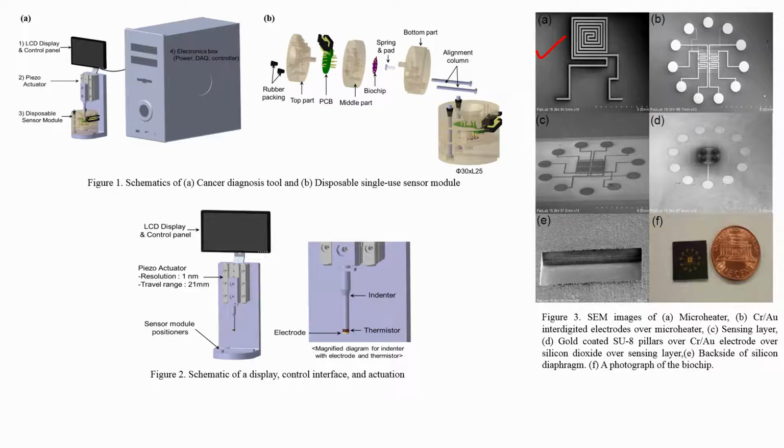After the heater you have an insulating material. On the insulating material you can have interdigitated electrodes. Once you have interdigitated electrodes, again you know how you can fabricate them. You deposit metal and use a lithography technique to form interdigitated electrodes. On these interdigitated electrodes you can deposit the sensing material, and this sensing material is your piezoresistive material.